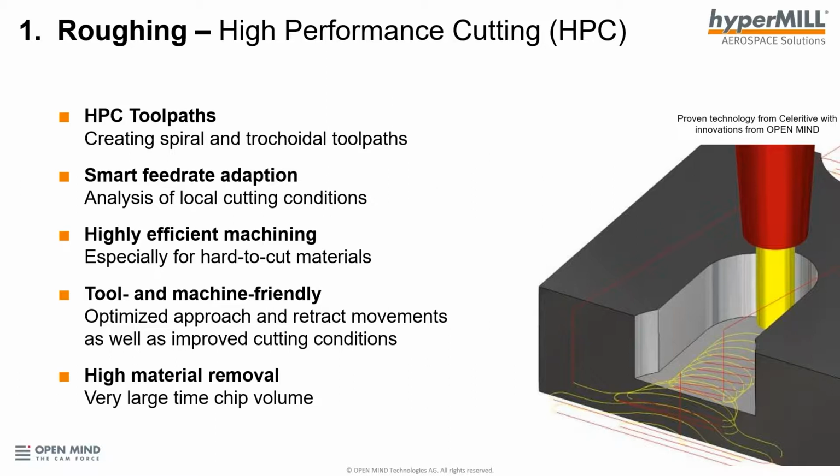As I said before, it's really nice on parts where maybe the spindle is slightly limited, or it could be a difficult hard material that you need to cut, or the fixturing or the part setup is not optimal. So it's a nice result, and it's gained quite a bit of traction over the last few years. But I would say it's not the quickest way of cutting aluminium, and that's what we're going to look at in the next result. But it definitely has a purpose, and gives you a very nice result.